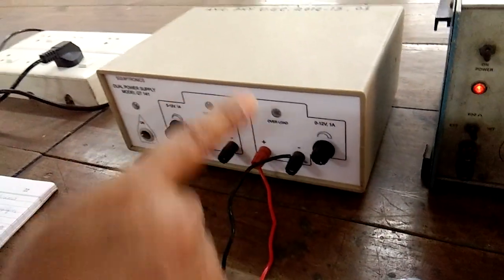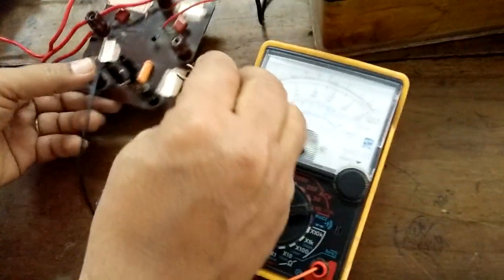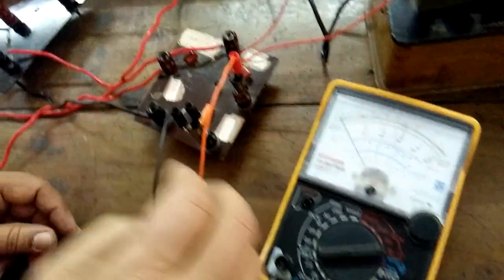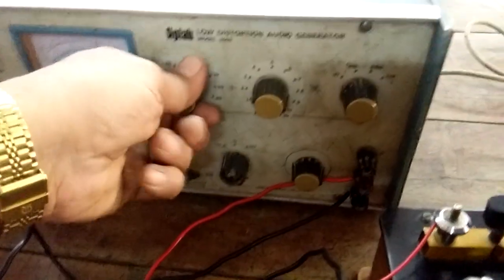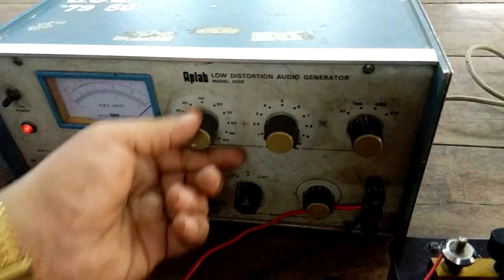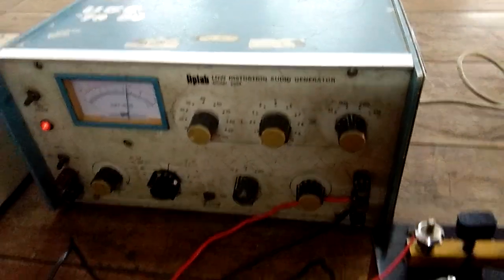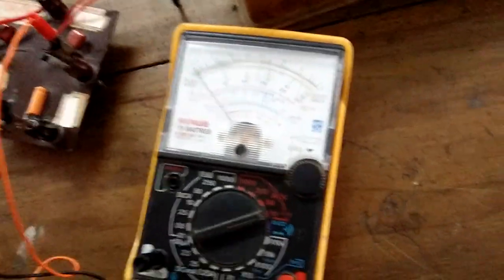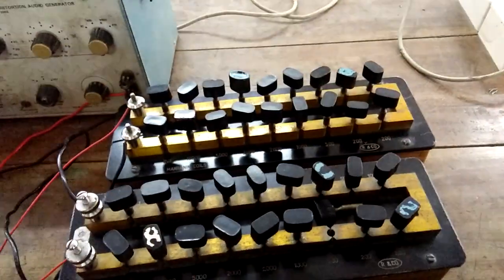Then from this battery, 9 volt is connected for biasing of this transistor. Connect this meter across these two terminals to measure the output. For input frequency, start with 10 Hertz, 20 Hertz, 30 Hertz and so on, and for these low frequencies we have to see the value of the output. First select here the value of RL from this resistance box.